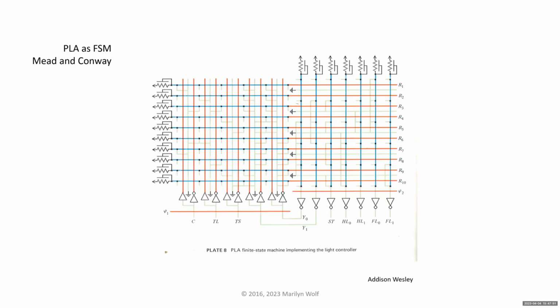Those are then connected to the OR plane, which you can see is rotated by 90 degrees. So we use the same structure, but rotated. We can build programming tabs to create the programming of the OR plane. We then use inverters at the output to make sure we have a nice, strong signal. Okay.